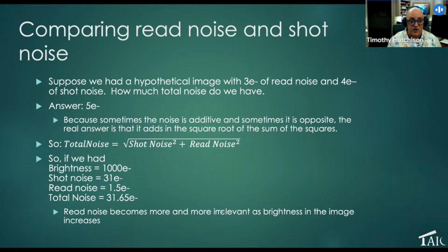Well, how is noise measured? The read noise we know is measured by the number of electrons per pixel per second, right? Shot noise is the same thing. Shot noise is that variation from image to image in the number of electrons that we've collected for that pixel. And it's measured in the number of electrons per pixel per second. Does that make sense? Makes sense to me.